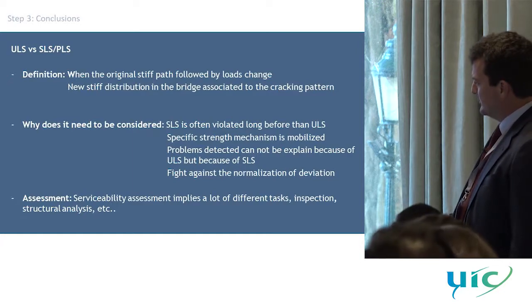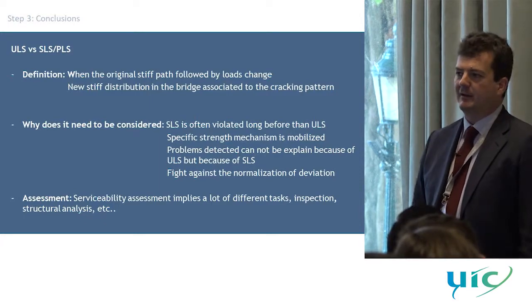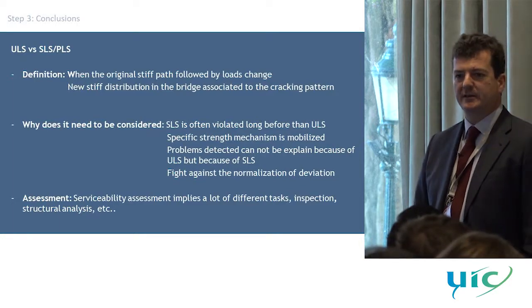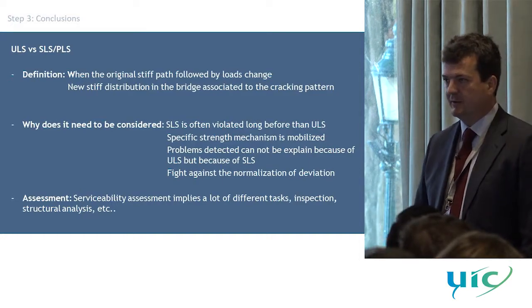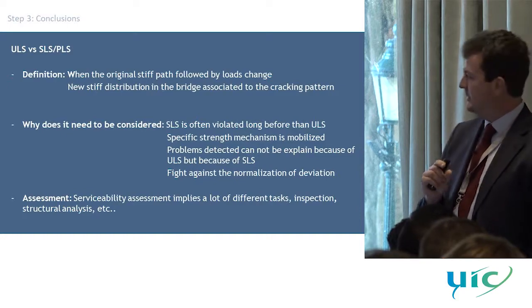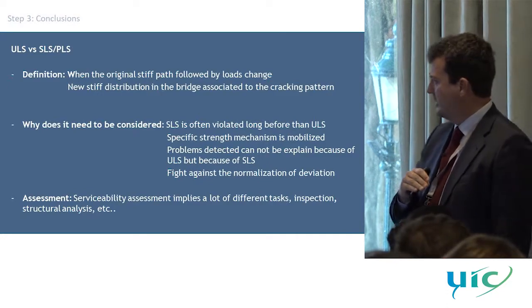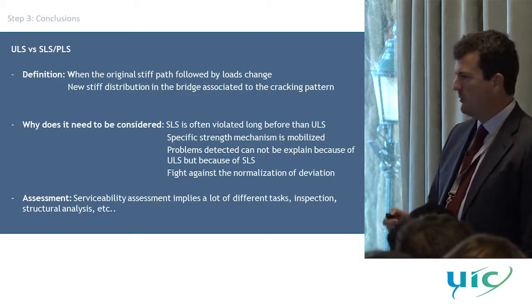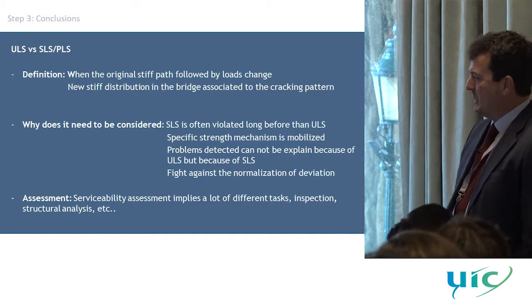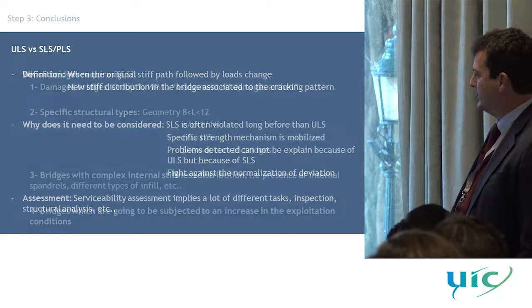And another thing that I think is quite fair to indicate is we normally try to solve everything by numbers, and for these problems I would suggest not using numbers. For me, 3D analysis is not a 3D model, it's a 3D analysis, maybe it's monitoring, maybe it's whatever it has to be. But it's very difficult to catch these problems with numerical analysis because, in my opinion, they are not related with the stresses that we normally use in our programs. You can use Abaqus, sophisticated, whatever you want, but the problem is not related with the stresses. The problem is related with compatibility and stiffness in the bridge. So sometimes doing a good monitoring, a very simple monitoring, can give you more information than many of these analyses.